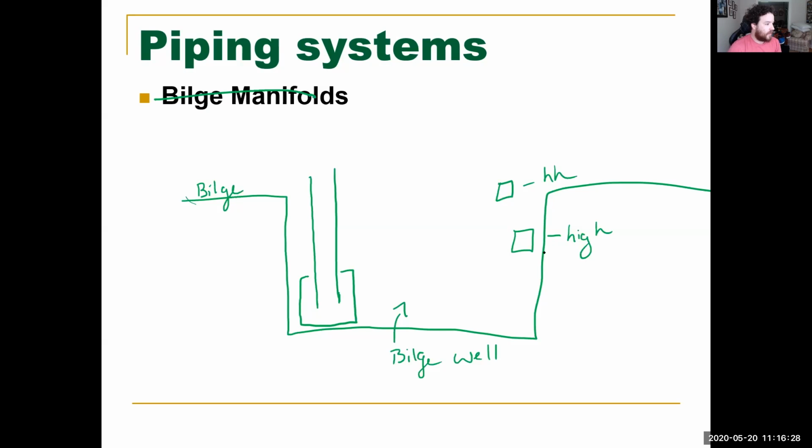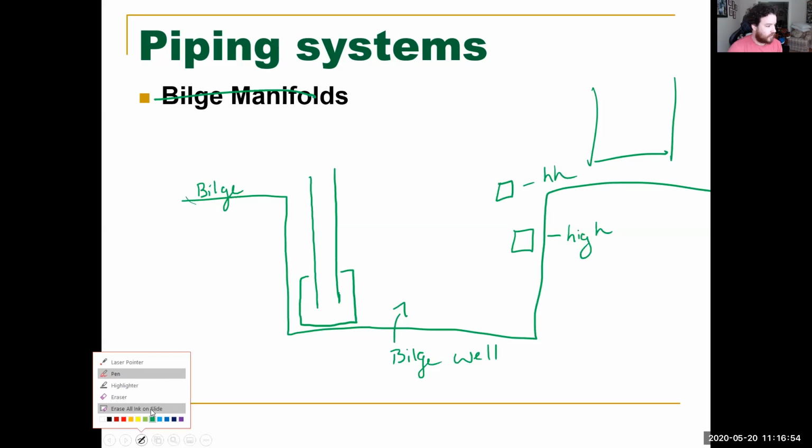All right. And sometimes you'll have bilge wells, like I've talked about, you can have that fire pump. That's the emergency bilge suction. Those aren't really going to go into bilge wells. If you're using that, you pretty much have a giant pipe with no cage. It's just sucking water and putting it overboard because you're in a bad situation. All right. That's a bilge well. Anybody need this up a little longer or can I erase it? You guys good? You're good.